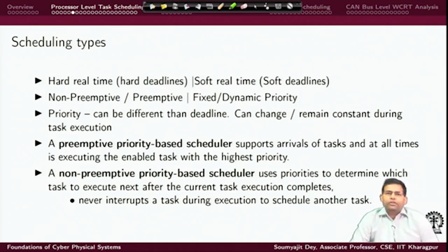Now, what is the priority of a task? The moment we talk about preemption, we are saying that one task can temporarily halt the execution of another task and execute itself. That means the task which preempts another task has some more importance. This idea of importance is formally captured using the notion of priorities.